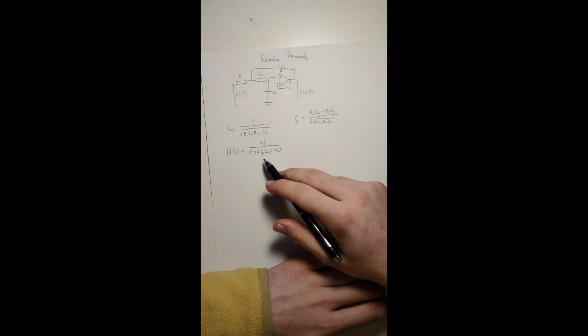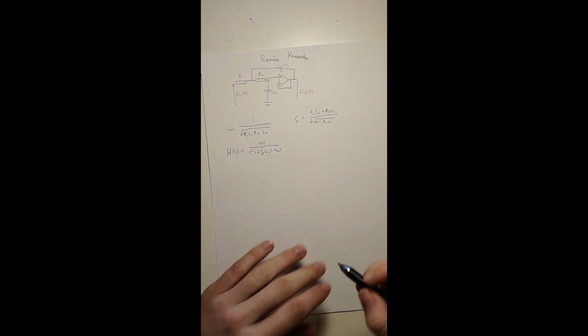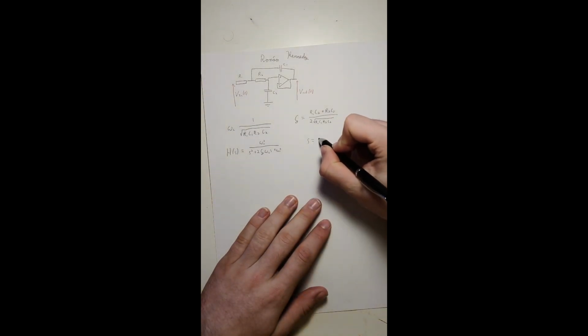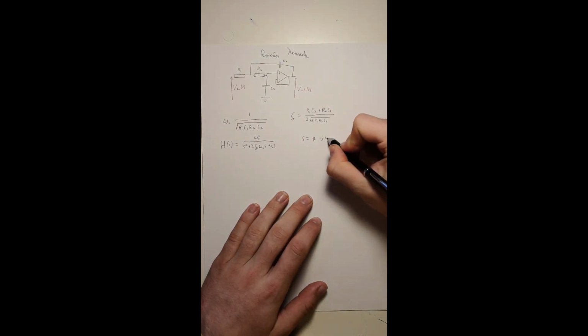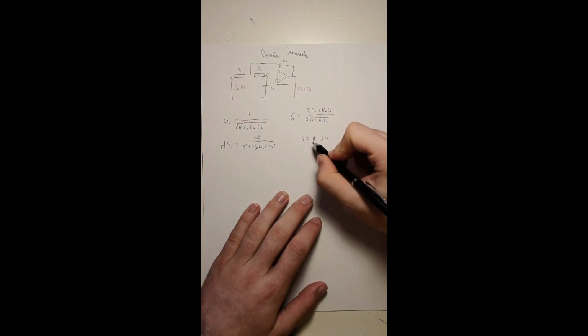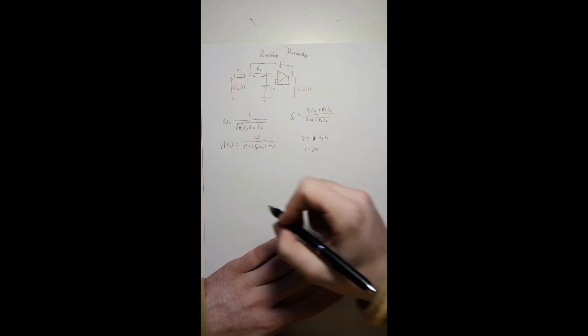So here we've got zeta and we've got our omegas. Now s is equal to sigma plus j omega. But when sigma is 0, so when sigma is gone, then s equals j omega, this is our frequency response. So we can write that in.